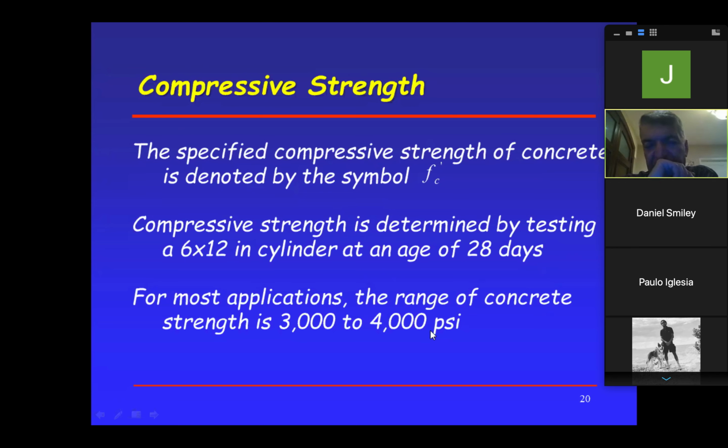I said that. Okay? But for buildings, definitely the 4,000. For foundations, 3,000, 3,500. In the project, I gave you that. I said 4,000 above ground, 3,000 below ground. Okay? And why? Because for the foundation system, we don't need as high a concrete strength. So we can save some money by doing that.